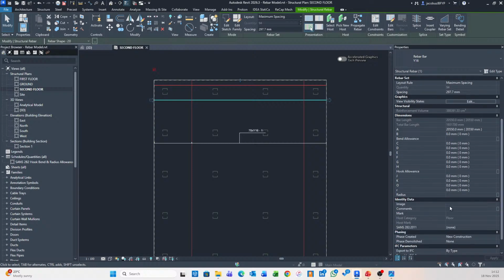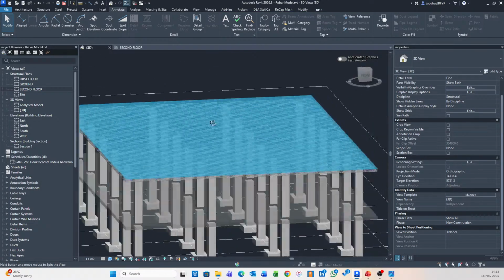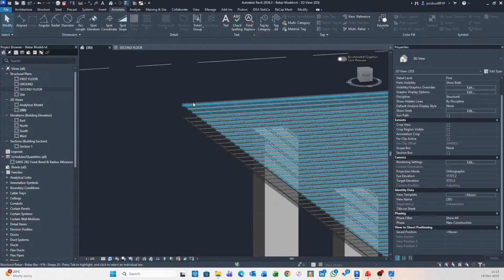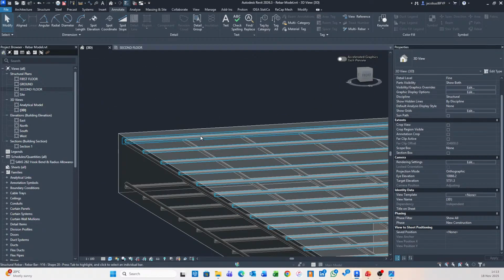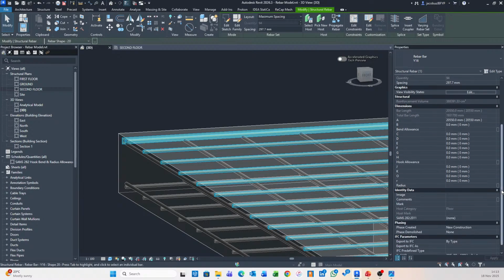Okay, something else to look at is something like comments, maybe where we want to set this as T01, T02, B01, and B02, or T1, B1 for top one, bottom one, etc. And that is quite useful. It's easier to do in something like the 3D view, where you can actually see, okay, this bar here is T01, and you definitely want to do this before you start splicing. Otherwise, it becomes an absolute mess.